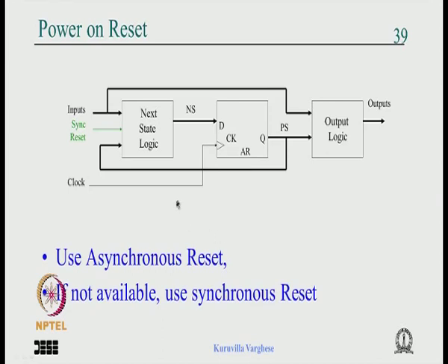We have to see how low we can go, because in terms of power dissipation that's the best thing to do. After all, the state machine alone cannot do anything. As long as it allows the data path to proceed at the desired throughput, desired frequency, then we should choose a frequency of the clock for the state machine such that the data path works properly at the desired performance.